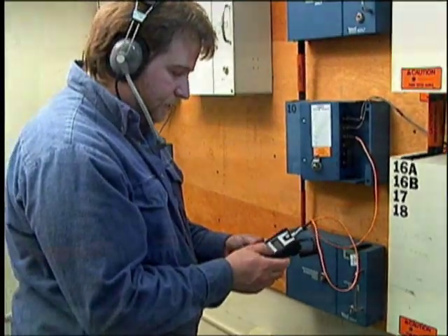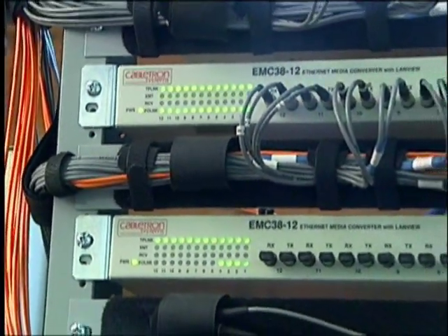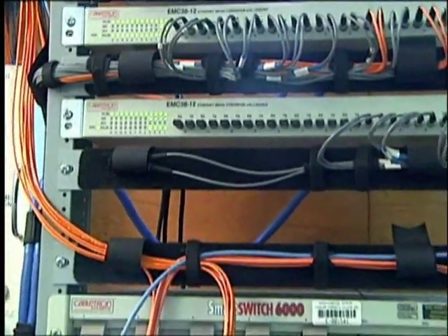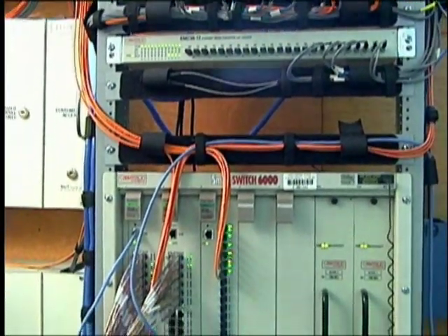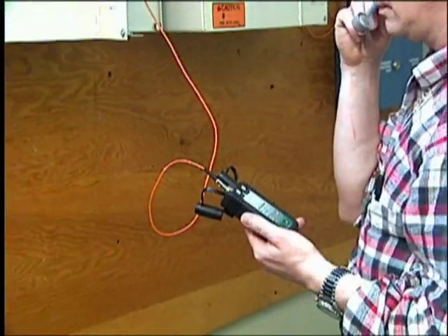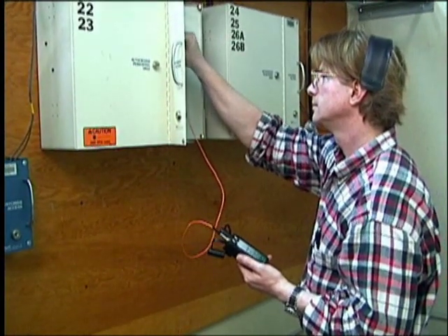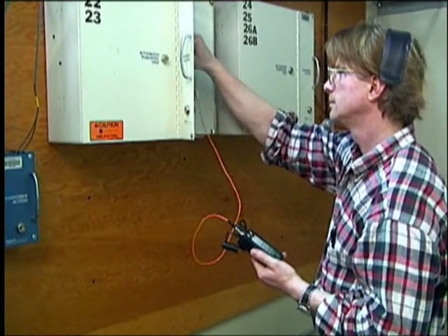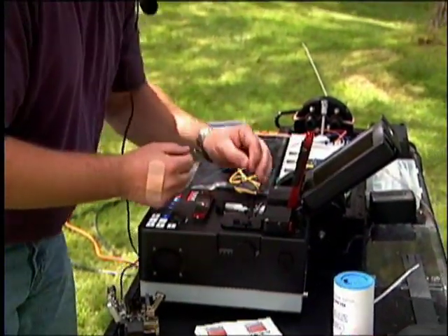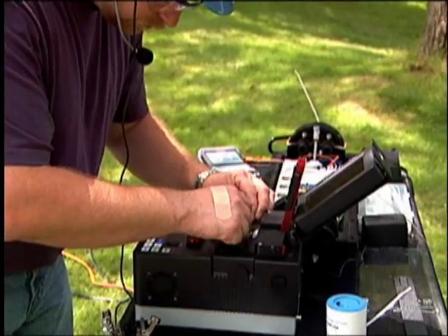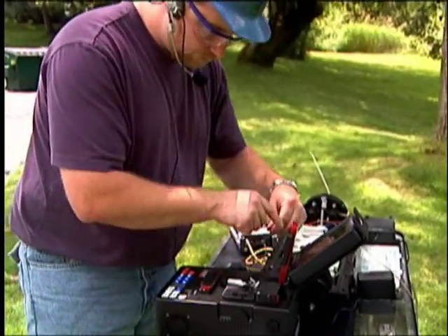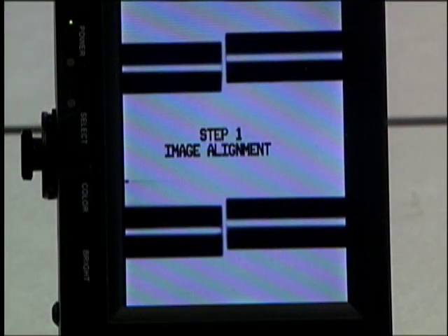Today's ever-increasing demand for higher speeds and lower cost per transported bit has led to the requirement that fiber cable systems be tested and certified for operation at higher bit rates. Loss measurements have become more rigorous, while at the same time they are being done by less expensive equipment that is operated by people with less specific training. As fiber tolerances have improved, we've seen specifications for splice loss decrease from 0.5 dB to 0.1 dB and less, making the measurement more difficult from a technical point of view. The demand for low splice loss is directly related to keeping transmission loss low to enable maximum bandwidth capability.